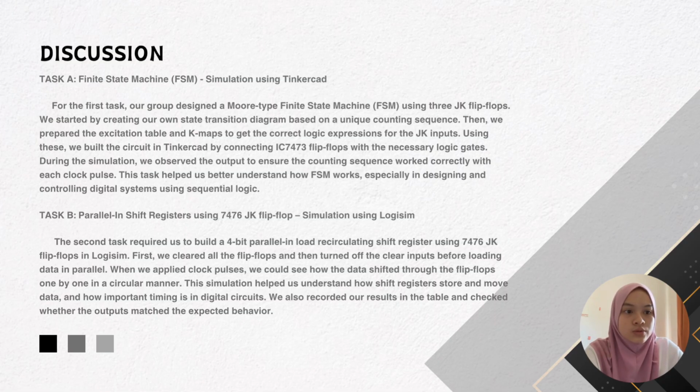Using this, we built the circuit in Tinkercad by connecting IC 7473 flip-flops with the necessary logic gates. During the simulation, we observed the output to ensure the counting sequence worked correctly with each clock pulse. This helped us better understand how FSM works, especially in designing and controlling digital systems using sequential logic.